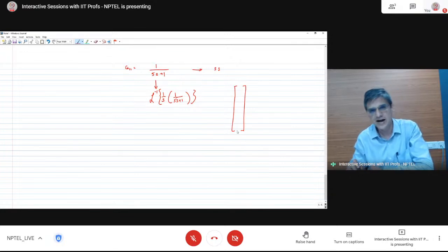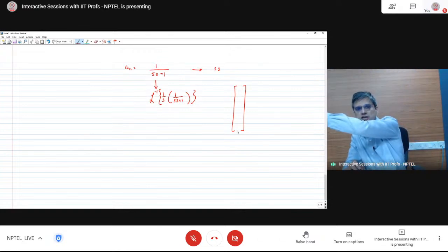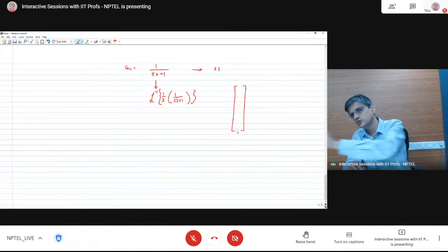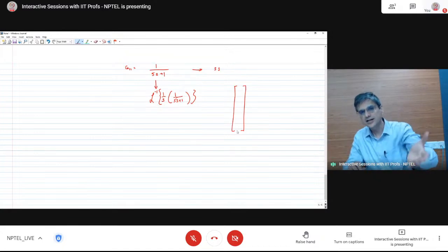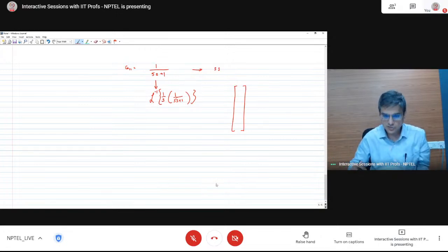How do you do this in MATLAB? You create transfer functions G11, G12 up to G1,100, G21, G22 up to G2,100, and so on up to G100,1, G100,2 up to G100,100, and then run a step response, generate step response coefficients using the command step, and then build your S matrix.